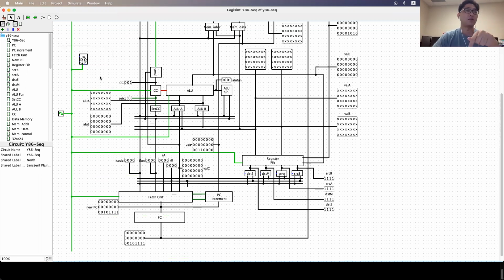Okay, what is the halt state? When the processor starts executing the halt instruction, it cannot move to another instruction. Then we will see the I code is always 0 after some time. Then we know, okay, this processor fell into the halt state. Then I'm going to stop ticking and then see the results, like in the register file and the memory.